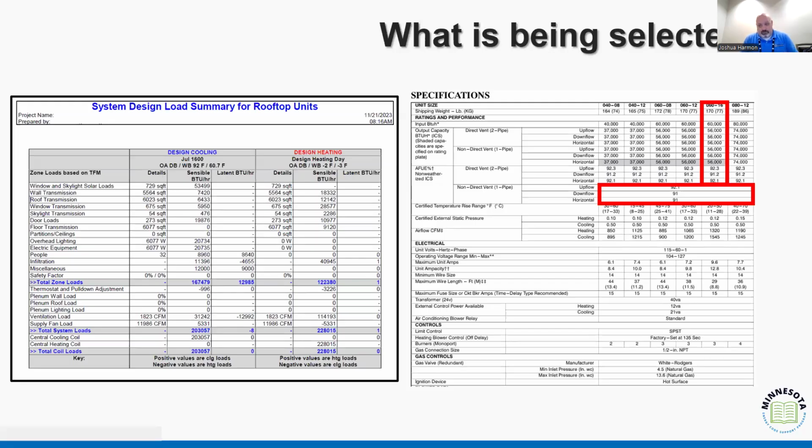what he thinks the load should be, shows it to the homeowner, or the homeowner then calls the city and the county and says, hey, I think you guys screwed up here because I've got a second opinion and my load is different. And part of that comes back to, well, did they look at the right piece of equipment? Did they look at the right design loads? Did they look at the right airflow modeling and the right distribution duct systems? No. Well, then you can't compare apples and oranges.